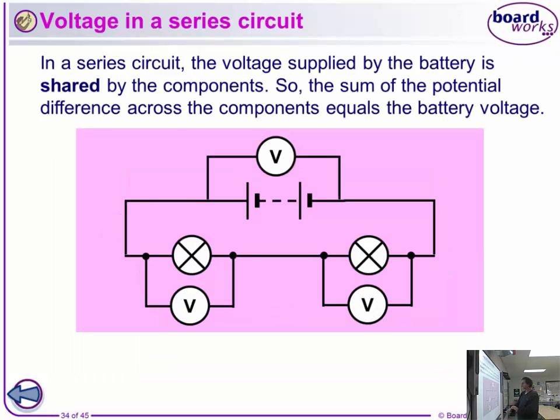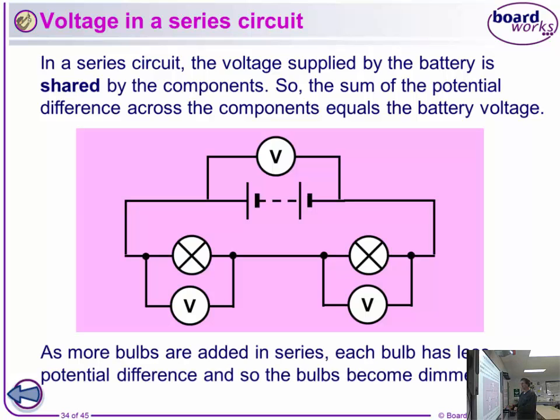You can measure the voltage across the series circuit here by putting a voltmeter around each of the globes, and then you can also check it across the power pack and compare the voltages here with the total being released here. As more are added there, you'll find more voltage is being used across each of the globes, but the total voltage coming out should equal the total voltage as you add them together across those globes.